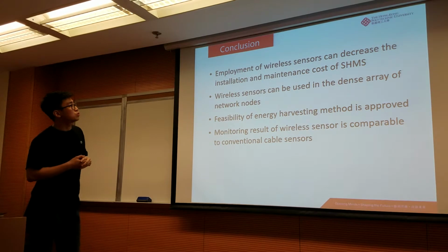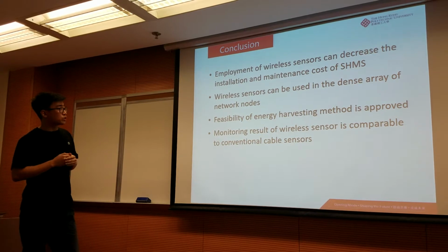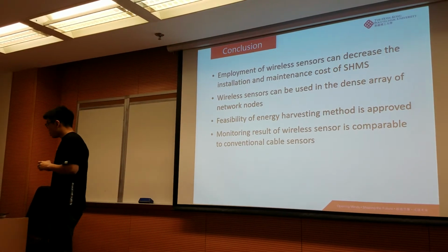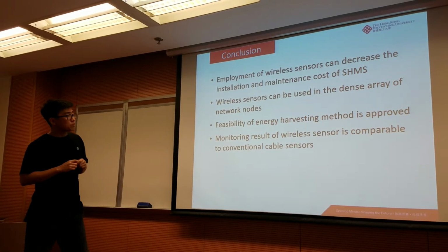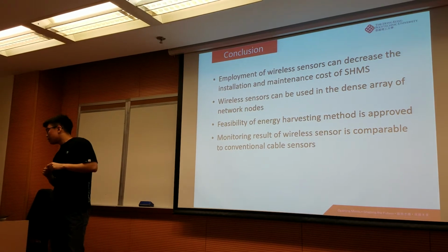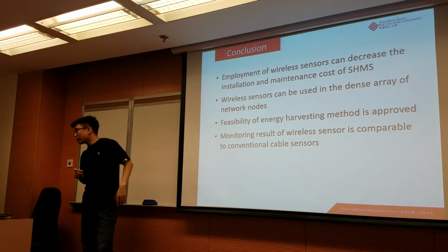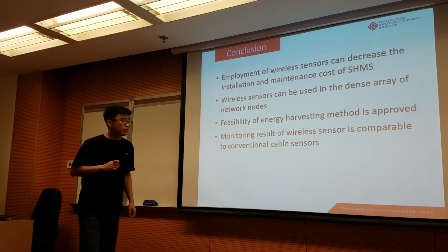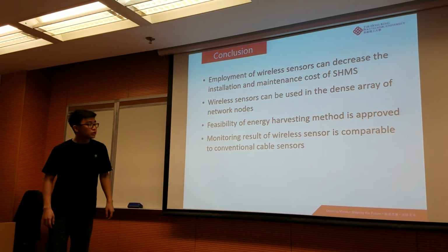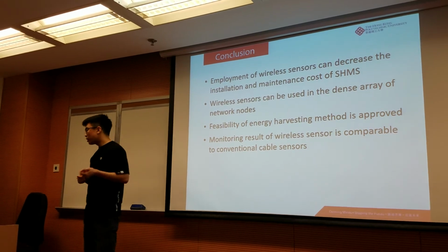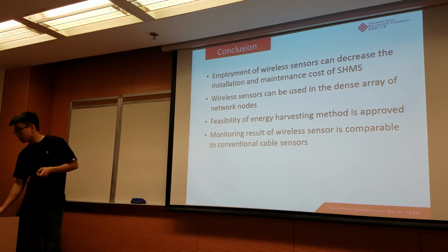So to conclude my presentation, the employment of wireless sensors can decrease the installation and the maintenance cost of the structural health monitoring system, and wireless sensors can be used in a dense array of network nodes. And also in this application, we can find that the feasibility of the energy harvesting method to power our wireless sensors is approved. And finally, the monitoring result of the wireless sensor is also very reliable compared to cable sensors.